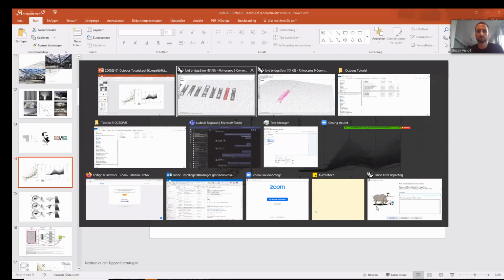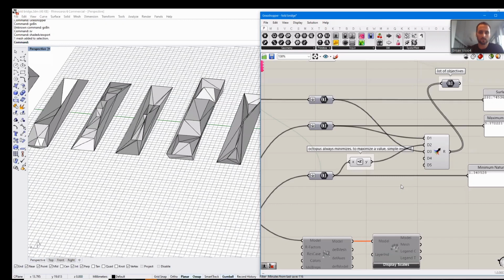In the viewport, you can switch the axis. So I can show all. I can show on all 3 axes. I can show the same goal. Obviously, it will be just a diagonal by changing those buttons here, how you assign, or which objective basically you assign to which axis. And there's axis 1, 2, 3, color and size. I can switch on the color. I can switch on the color and size just for some of them. If you do all the same, it goes from green to red and from small to big.